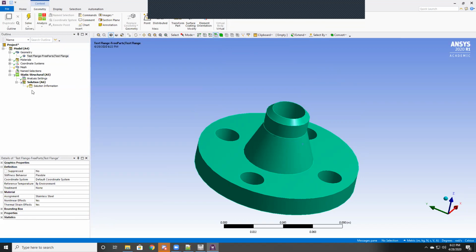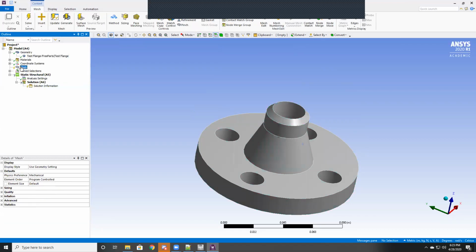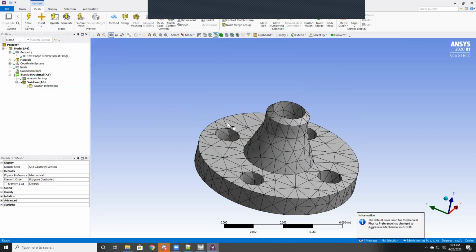In structural and meshing, it's usually down here. Fluent, sometimes it's over here. And in that panel, you change the settings that'll affect the mesh or the actual solution that it's finding. So we've set the material to stainless steel, and now we're going to go to the mesh. Right now, it just has base settings, and we can go here and click Generate Mesh on this ribbon bar up here, and it'll run, and it'll make this.